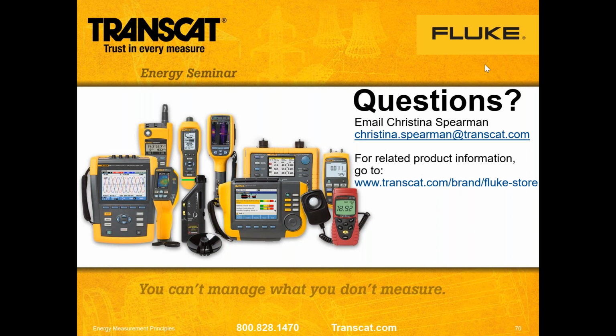So if I can reduce leaks, I can reduce runtime, it's going to reduce energy usage. So that last illustration we used for the lift truck manufacturer is a perfect example of what we're seeing. So we use a combination of a power analyzer and an ultrasonic leak detector to actually be able to quantify that dollar number to show real energy savings.